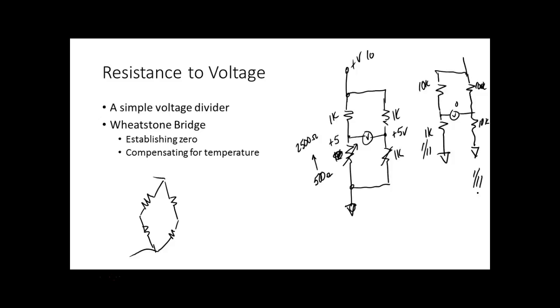So what we're looking at on the Wheatstone bridge is not that the resistors match. It's the ratio of the resistors have to match. Y'all understand over here? So I could leave this as a 1K, and I could leave this as a 1K. Well, I could change this to a 10K on this side, right? Well, what I would have to do on this side, if I adjusted this up to 5K, then we would say the bridge would be balanced. Because across the center, if the ratio is the same, the bridge is balanced.